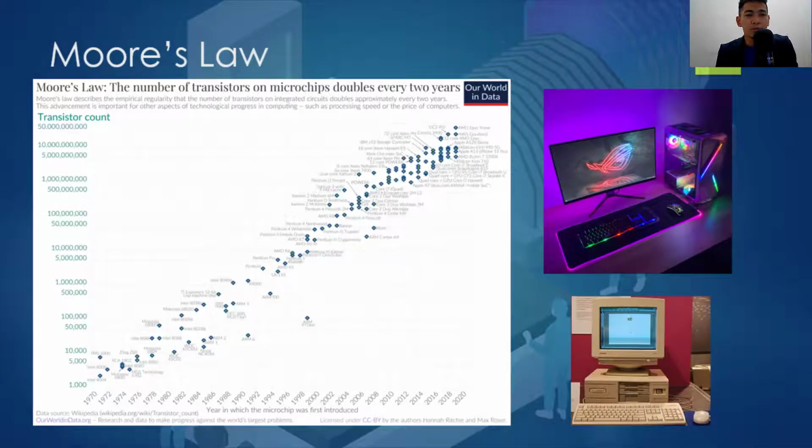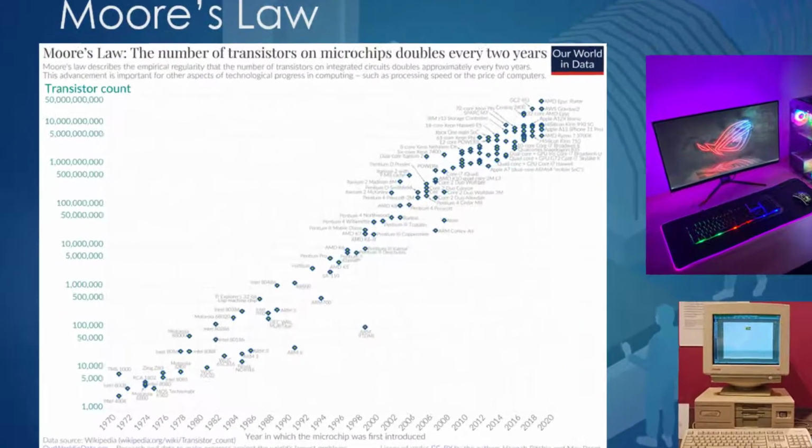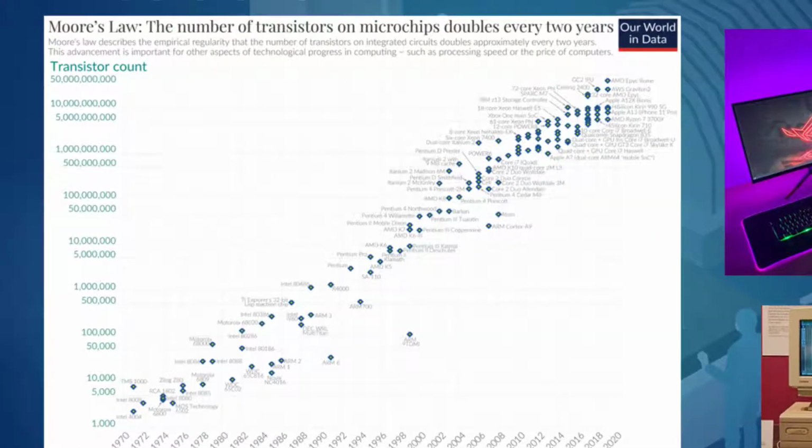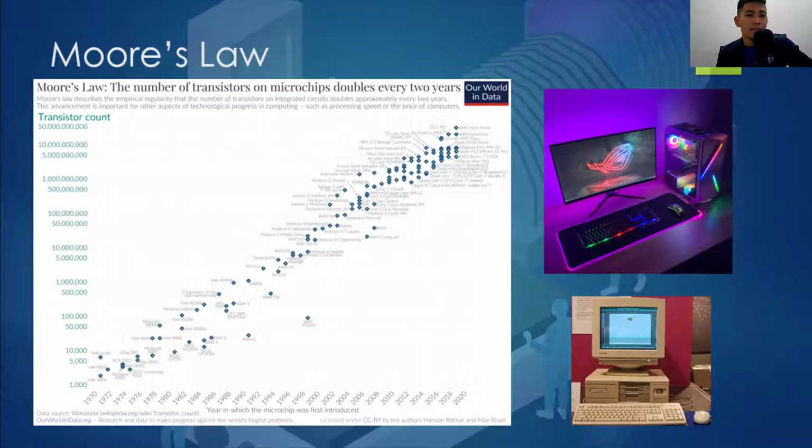We may want to first start with Moore's law. Moore's law is not derived from the laws of physics, but rather an observation by Moore that the number of components, mostly transistors, in an integrated circuit doubles every 2 years. Unlike other laws in economics or sociology, Moore's law did not use any empirical evidence on the continuation of the forecast of these historical trends. It has been used in the semiconductor industry to target their research and development plans. Examples of this are advancements in shrinking the size of sensors and increasing memory capacities of DRAM and flash, and digital electronics are linked to this law.